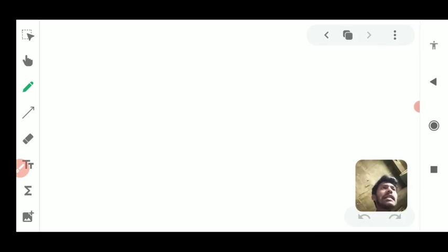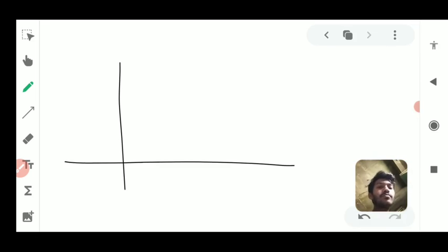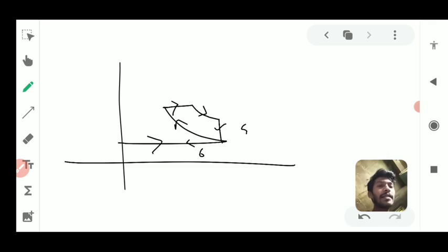Now there is another engine which is called the diesel engine. In this, all the processes are the same, but the third process is isobaric instead of isochoric. So this will be curved like this and then again back to this. So first, second, third, fourth, here it is fifth and sixth process. It also has 6 processes, and again we can ignore this part. We will consider only this part. The heat will enter from this and go away from this. So this is Q in and this is Q out.